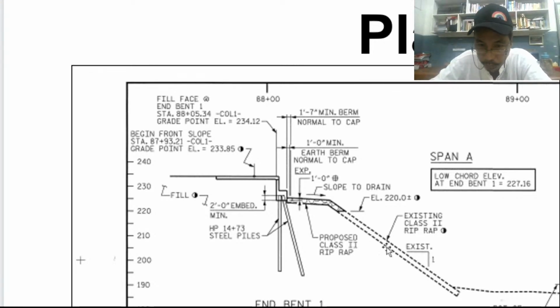There are several types of riprap. So this is just class 2. So there is a definition for class 2 riprap. So we can confirm it online right now. Class 2 riprap. What do we mean by class 2 riprap? That is a definition. Okay. So class 2 riprap, okay, may have what? Size 24 inches down to 12. Use erosion control. Okay.